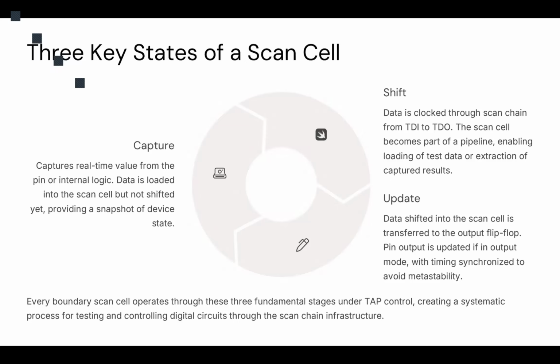Basically, there is a clock, and when we enter the testing vector, based on the rising edge of the clock, that testing vector shifts bit by bit through all those scan cells that are connected in series, and on each falling edge of that clock, the TDO observes the value of those scan cells.